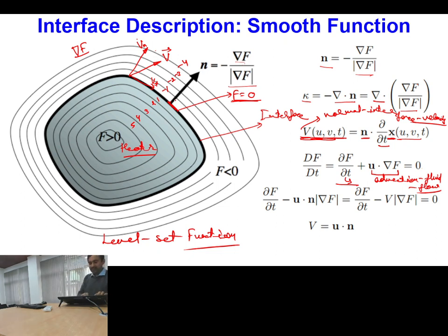Okay, if there is condensation, then mass will be changing from vapor to liquid, and there can be contraction if I consider this to be a vapor phase. Other than advection, the phenomenon of any chemical reaction or phase change can also lead to movement of the interface. Provided there is no phase change or reaction involved, the movement of the interface will be purely because of the advection of the fluid.